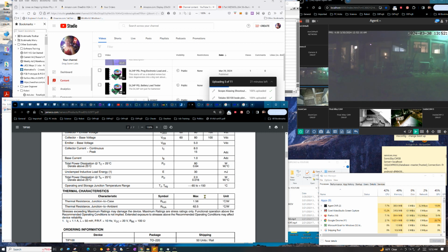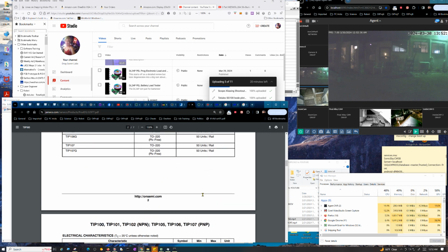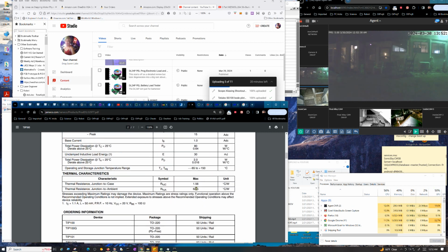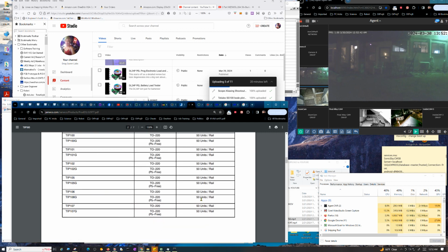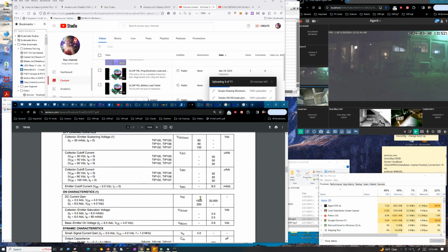And you want it to be close to the transistor, but if you have a heat sink on it, it can get a little more complicated. Still the same concept applies: you wouldn't want to measure the temperature of the heat sink itself. You want to measure the air that's going to be cooling the heat sink most immediately. So it would still apply, but if you had 1 watt in your transistor, it'll raise the temperature by 62.5 degrees. Okay, but that's above ambient.